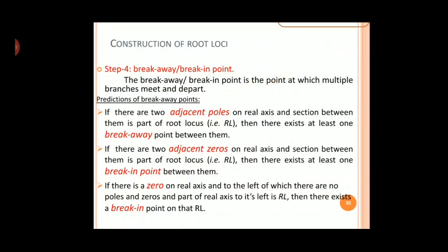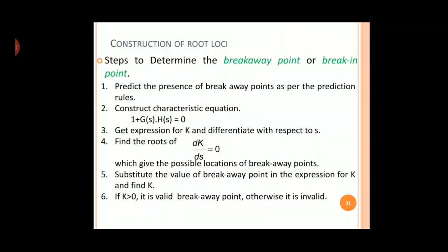Now here is a note: a breakaway or break-in point always lies on the root locus. In the previous case we had the centroid, which may or may not lie on the root locus, but a breakaway point always lies on the root locus. Now the prediction just gives an idea where the breakaway point can be. There are steps to be followed to really calculate the exact value of the breakaway point.